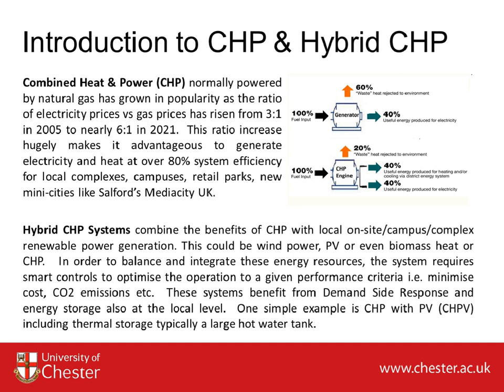the distribution system. Whereas if you could generate locally, which means that you don't have those transmission losses, and you take that fuel in and you have your generator local and it produces heat and power, you don't have to lose the heat. And up to now, with the state-of-the-art Jenbacher engines, natural gas engines, we're achieving system efficiencies, heat and power, of over 40%.